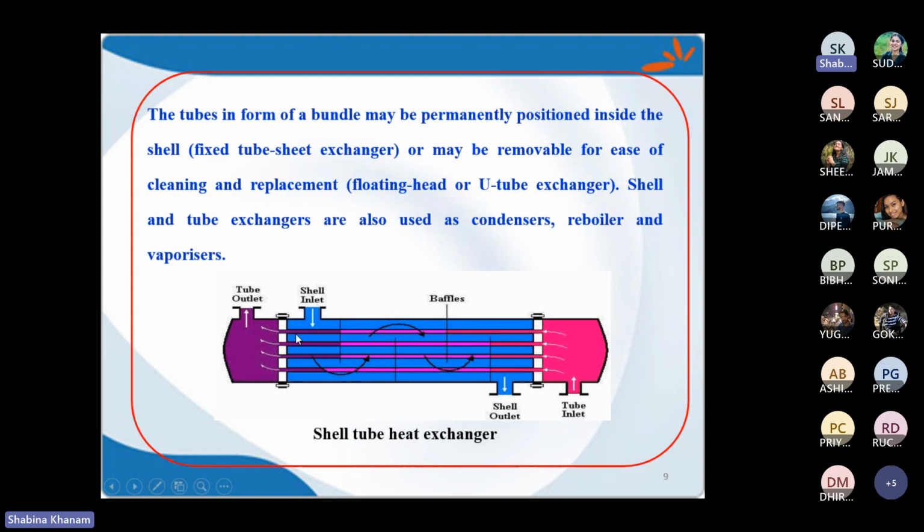And on that tie rod we put the spacer, which is basically a hollow cylinder, having a larger diameter than the tie rod so that it can be properly inserted. The purpose of a spacer is that it will cover only this much distance. Once I have this much distance, if I place the baffle, it will take its position up to here. Beyond that it cannot move.